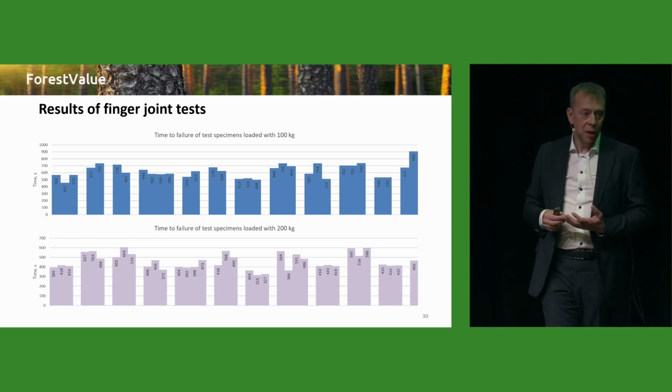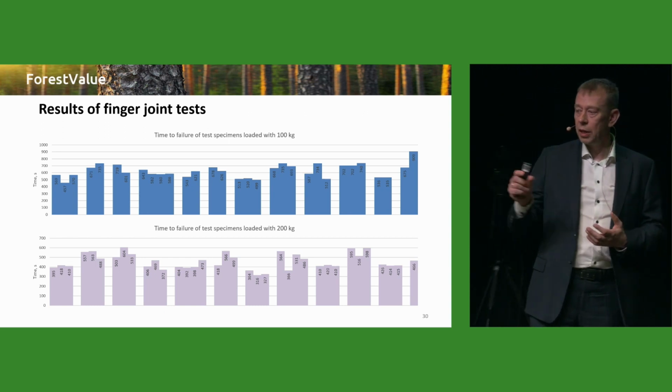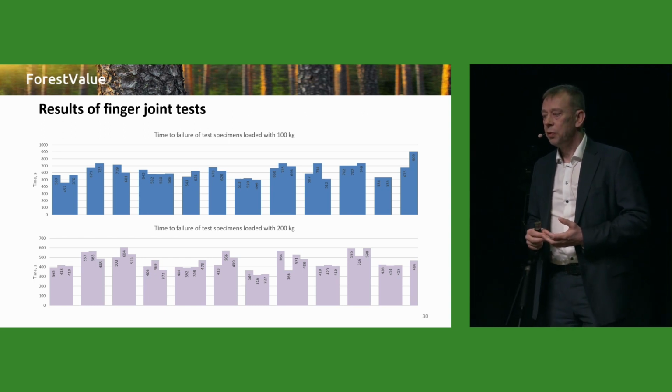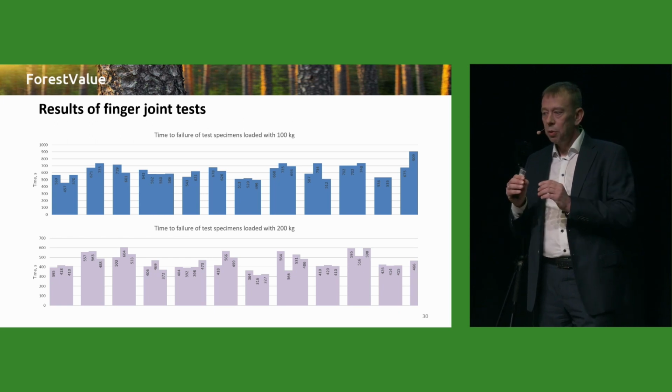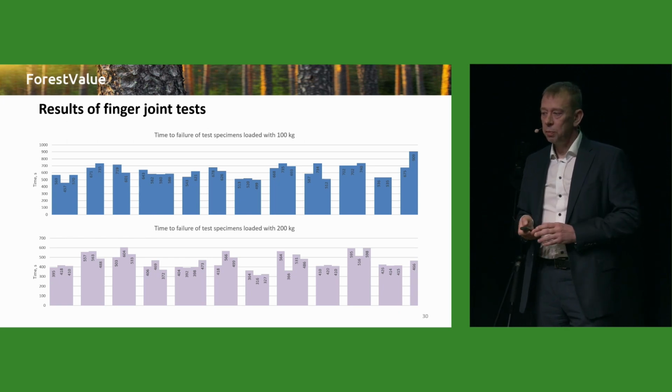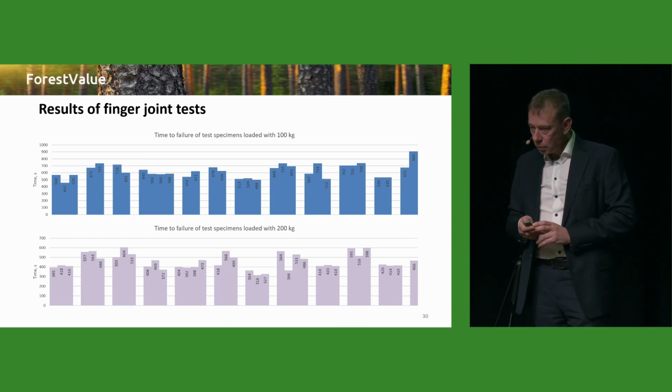Here we have all these 11 adhesives, the results from this small-scale finger joint testing under different loads, 100 kilos, 200 kilos. So every set is a different adhesive. You see there is quite good repeatability within the group, but there is some difference between the groups.